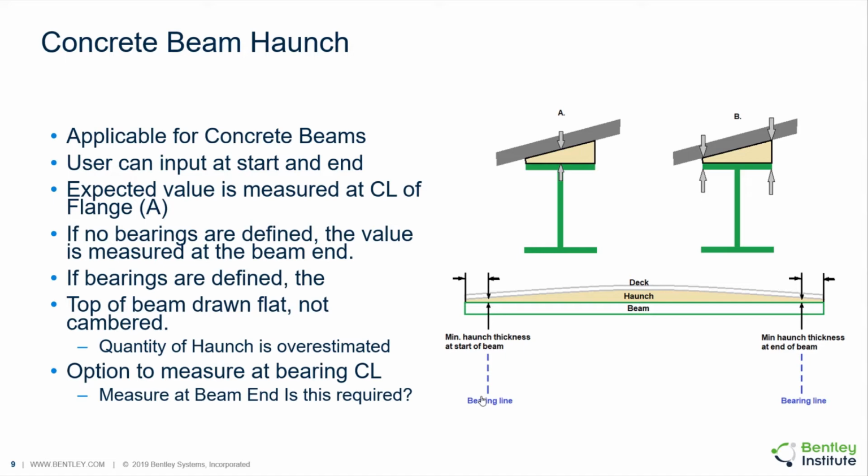Before it was only one, applied to all the beam. But if we have elements like bridges on a vertical curve, it was a matter of even playing with the numbers to get what we need. Right now, you can specify two different hunches, one at the beginning and one at the end, and we just compute it.